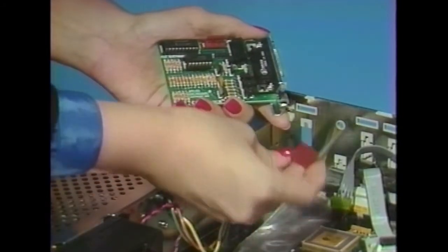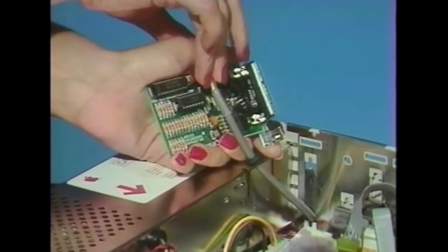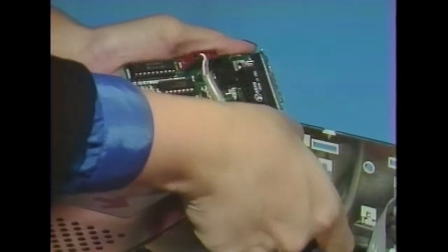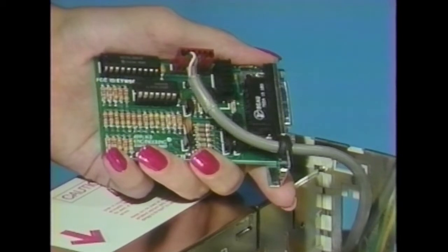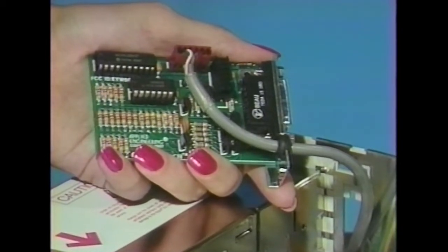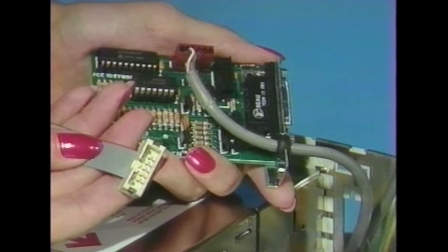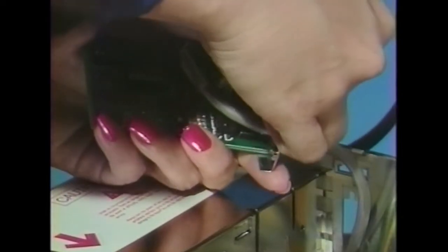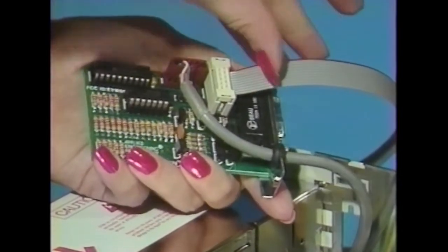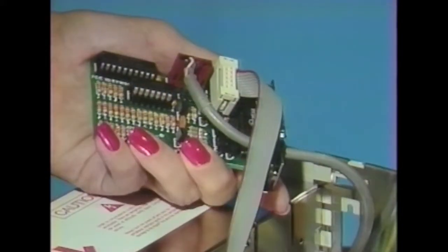The connector will attach easily in one direction only. Make sure all 6 pins are connected. Now push the strain relief grommet into the mounting plate on the color switch. The lips of the grommet should be flush against the outside surfaces of the mounting plate. Locate the 10-wire cable with male 10-pin connectors on each end. It looks like this. Plug either of the male connectors to the female 10-pin connector on the color switch. The cable's stripe will be toward the top edge of the PC transporter.